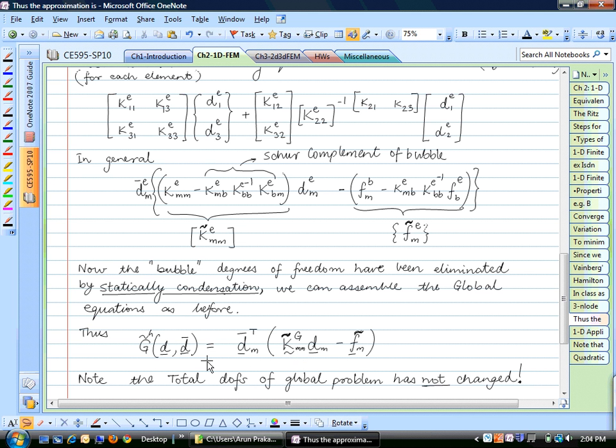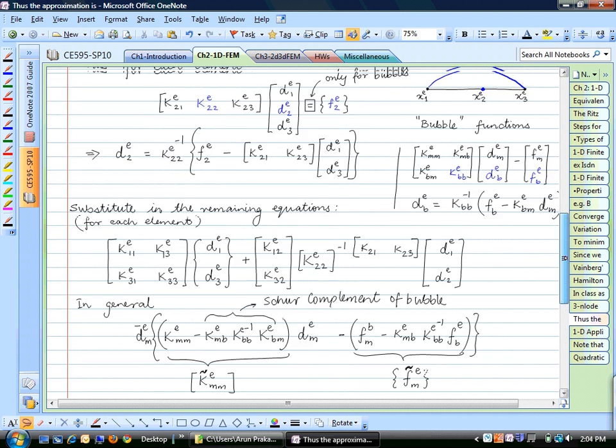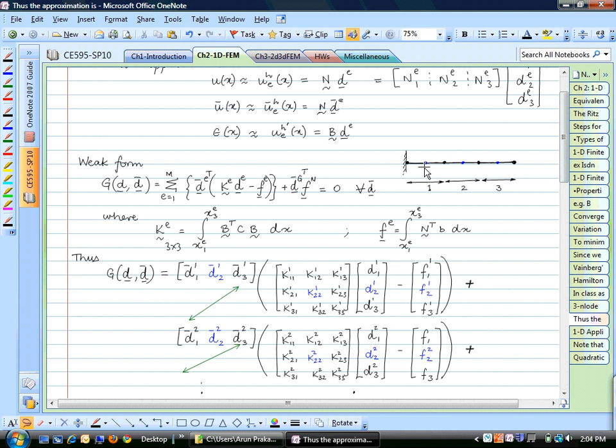So once you have this, you can actually just solve for the main mesh degrees of freedom. And that would mean that you would solve for this, which is fixed. You will enforce this boundary condition the same way that we divided it into two parts, specified and free, and so on. So ultimately, what you would be solving for is this degree of freedom, this degree of freedom, this degree of freedom, and this degree of freedom.